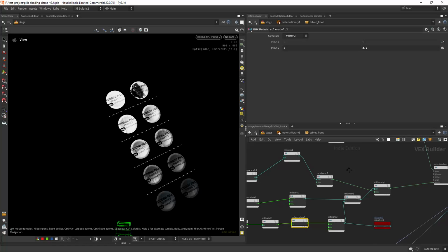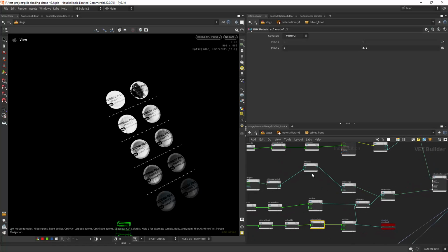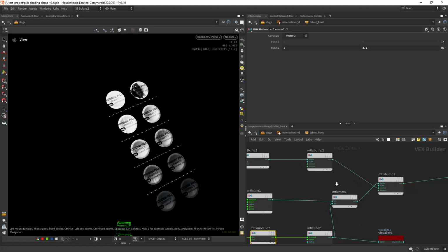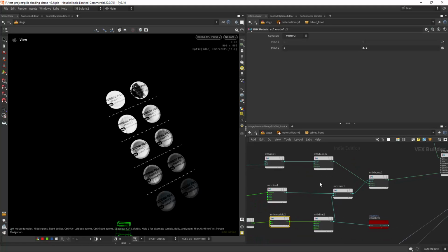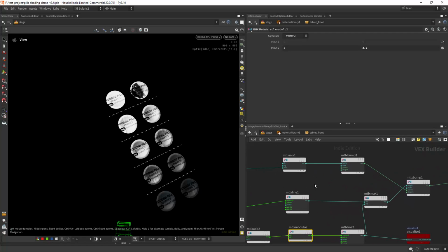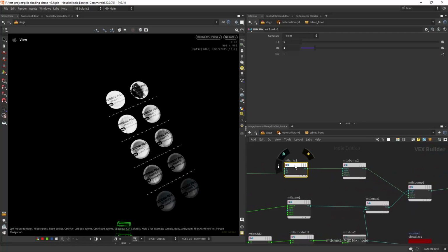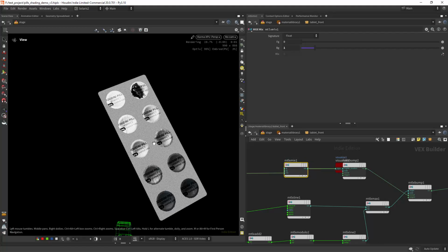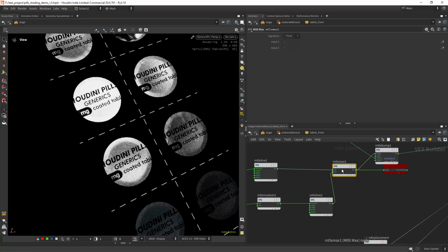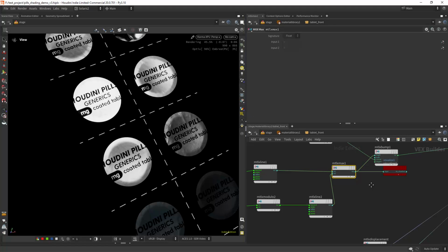And the final tip is on how to layer bump maps or normal maps, how to combine them, how to blend them. This is actually pretty simple. As you can see, I have this pattern in here and these maxed lines that I just use a MaterialX Max to combine both in an additive mode.